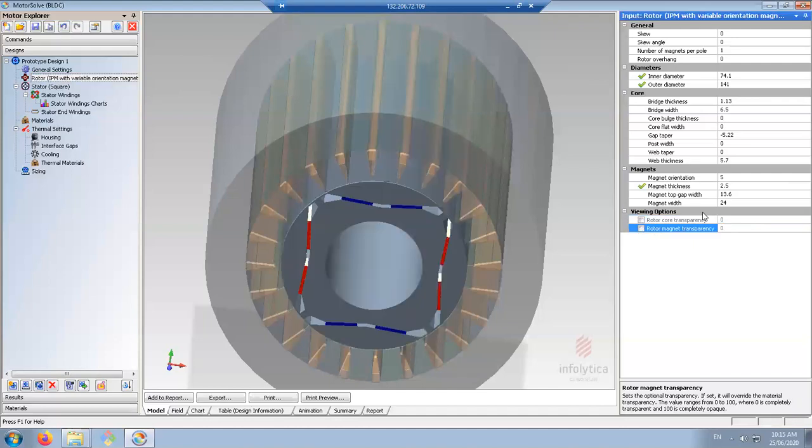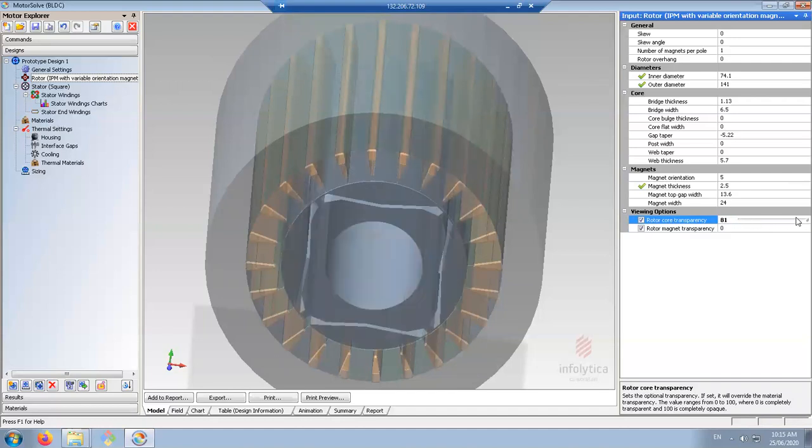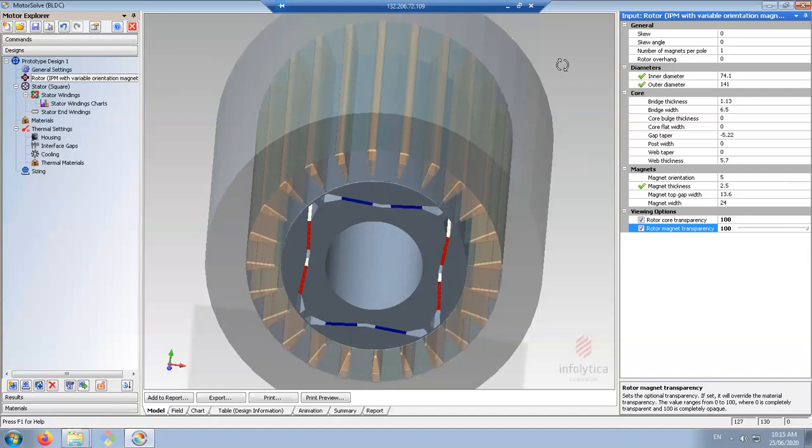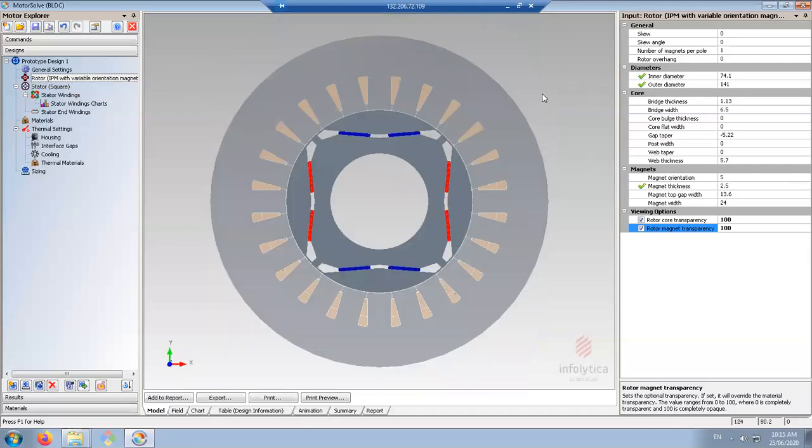So, for example, if you have a wind turbine high aggregation, which is actually a double fed induction motor or generator, there you will need to definitely apply skewing to the rotor or stator. Don't apply skewing to both the rotor and the stator. One would be enough.